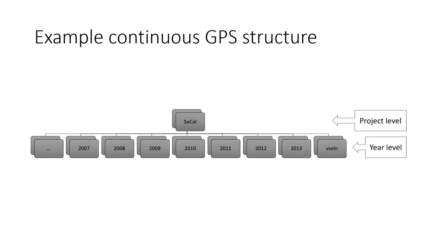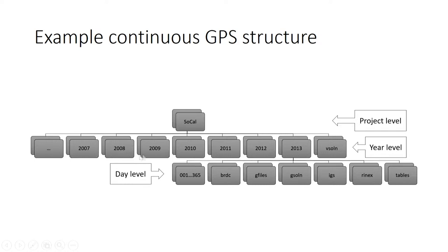And when you are going for this GAMIT processing, you have to make so many folders. For different year data processing, you have to make folders like this. Suppose this subsection is for 2013, it will have this BRDC file where it will keep navigation data. Then here it will keep the orbit file, here the solution, and here the sp3 file. RINEX files from IGS stations, from your rover station, base station, all those data will be here in this folder.